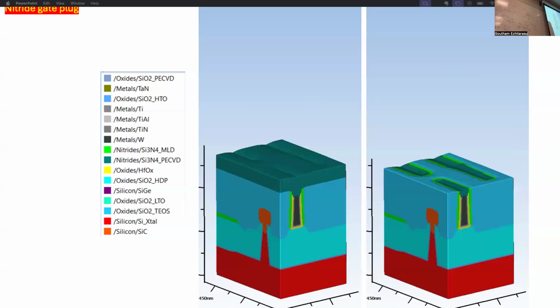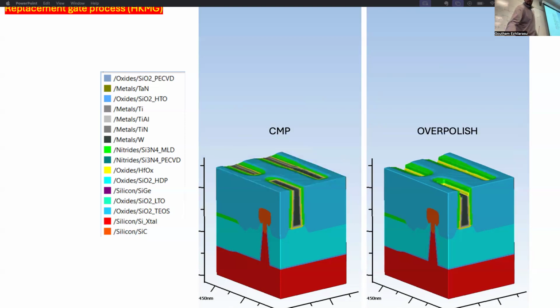How did you CMP the tungsten down so deep? Oh, because you can CMP tungsten. Compared to nitride, it's soft. We had a very high stack, right? But in this case, our tungsten is dished way lower than oxide. Right, can we go backwards? Is this black right now, the tungsten, right? Yeah. No, there is a nitride here, by the way. It's below that. Oh yeah, this overall. How did we get that?